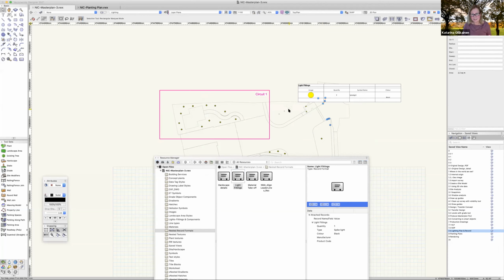So each of these planting beds is its own viewport, and you can then go in and put on your data tags. This is the one place I say that you can go away from this rule about placing all your annotations on the sheet layer, because a lot of times it can be easier to actually do it on the design layer when you have separated the beds. The reason is because the plants themselves have a tag in the tool. So each plant, you can just use the plant tag directly from it.